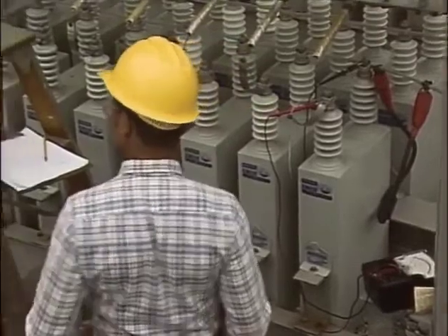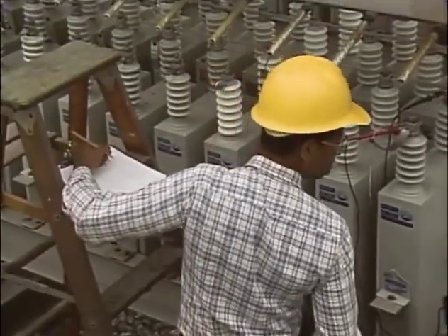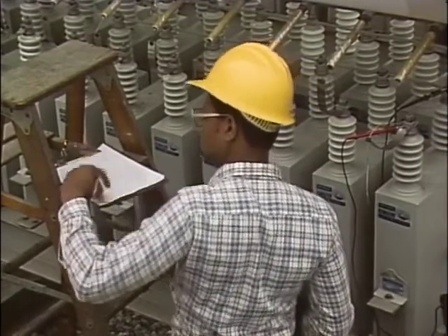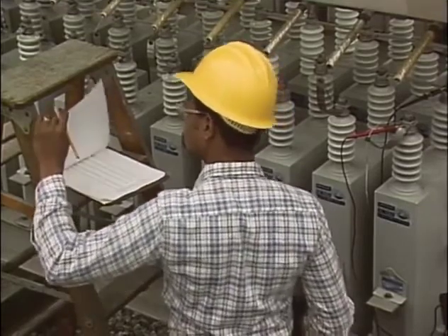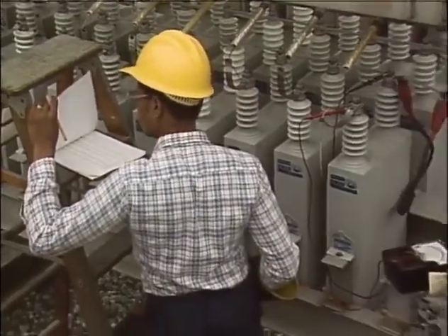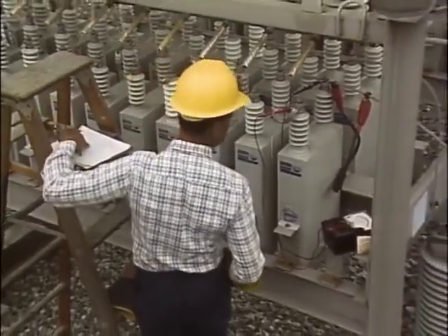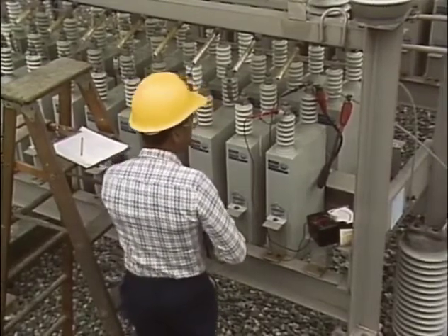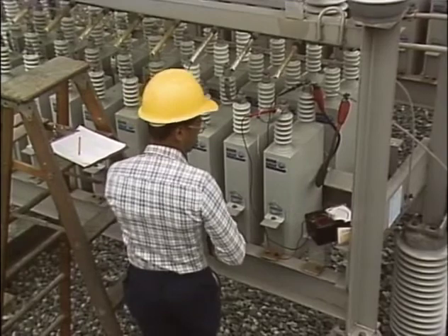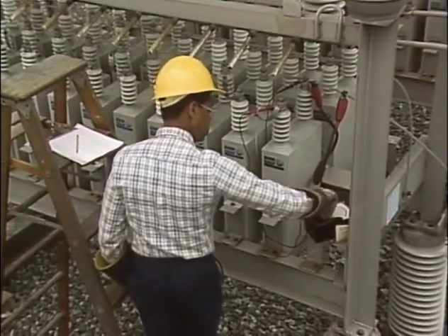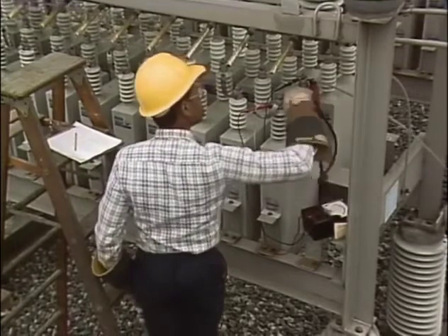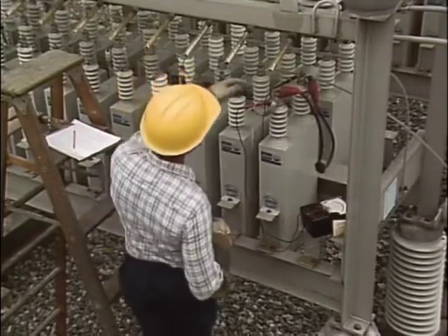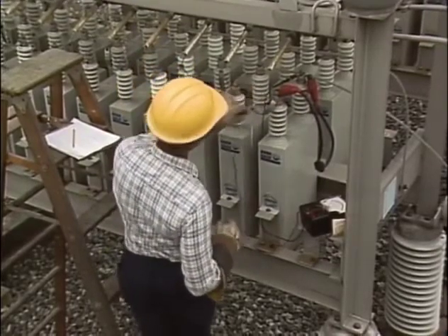Some companies require that the reading be taken at a prescribed time after voltage is applied. This results in readings that can be compared over time and that can be compared with readings for other capacitors in the bank. The resistance reading can also be checked against the manufacturer's rated resistance for the capacitor. If the resistance is not within an allowable range, the capacitor is typically replaced. After the test is completed, the multimeter can be turned off. The capacitor should be allowed to discharge through the bleed resistor for several minutes before the short is reinstalled on the capacitor. Finally, the multimeter is removed from the unit.